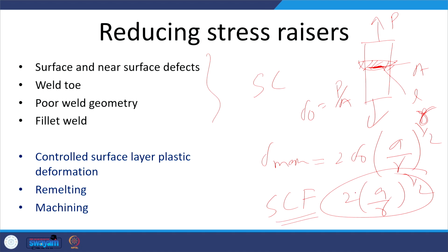So the maximum stress will depend upon the size of the defect and the tip radius. Therefore, it is very important that these defects are either modified or eliminated.